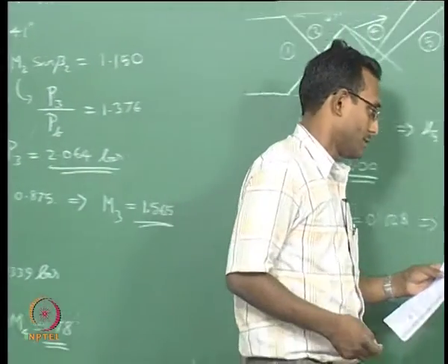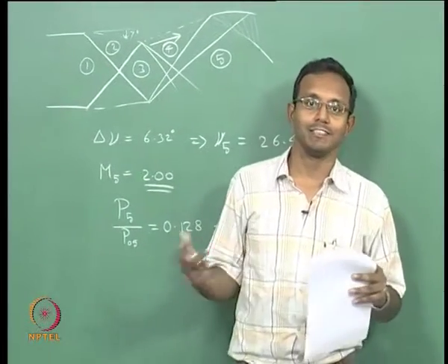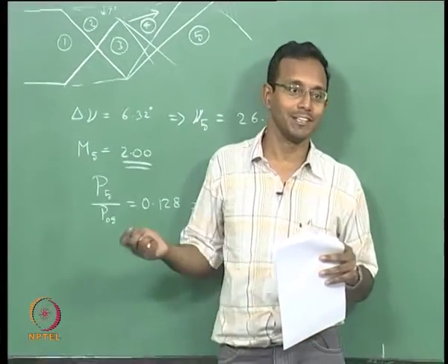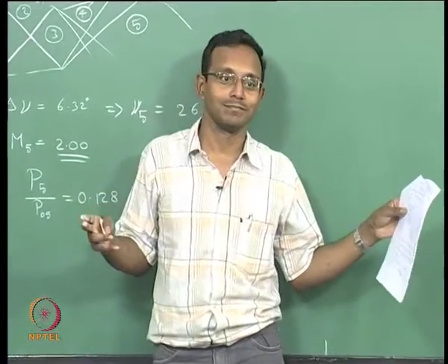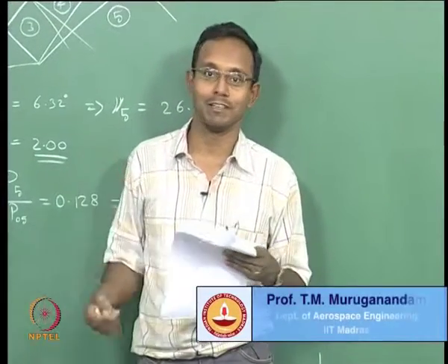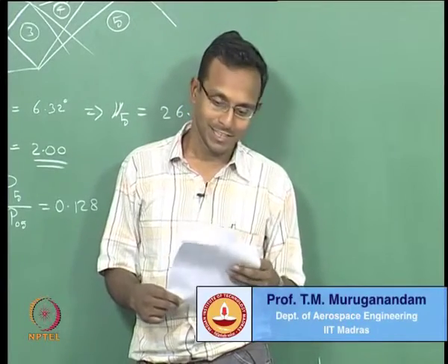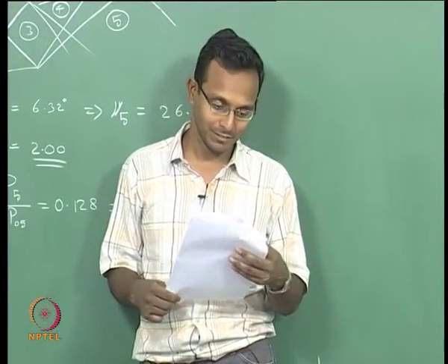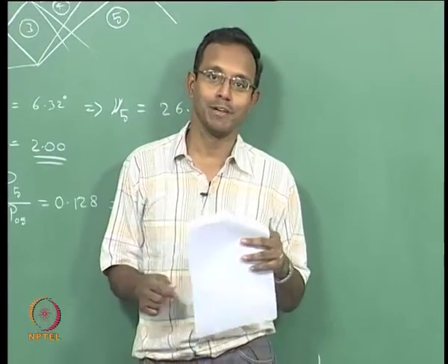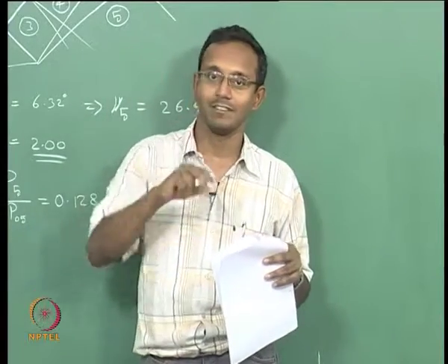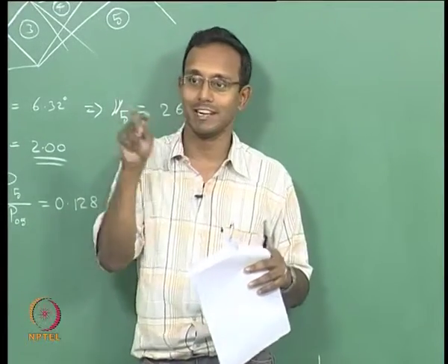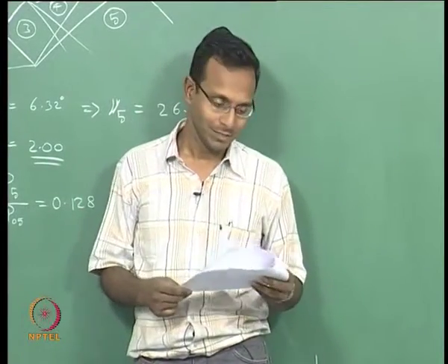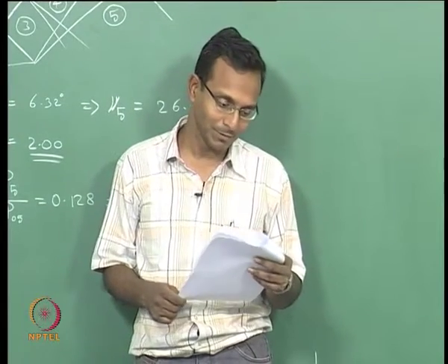Okay. So when you are getting results like this, of course you have to now think about whether your calculations are accurate enough. Now you can say that your error band is really wide. You are getting results more than what is possible theoretically. So that is not possible to have happen ever. There is some error somewhere in that. And it is most likely because I approximated beta from looking at a chart which does not have so much resolution. My grid levels are like 2 degrees. I am resolving it into 0.2 degrees, 0.5 degrees kind of numbers. Not very good. That is where we had problems.